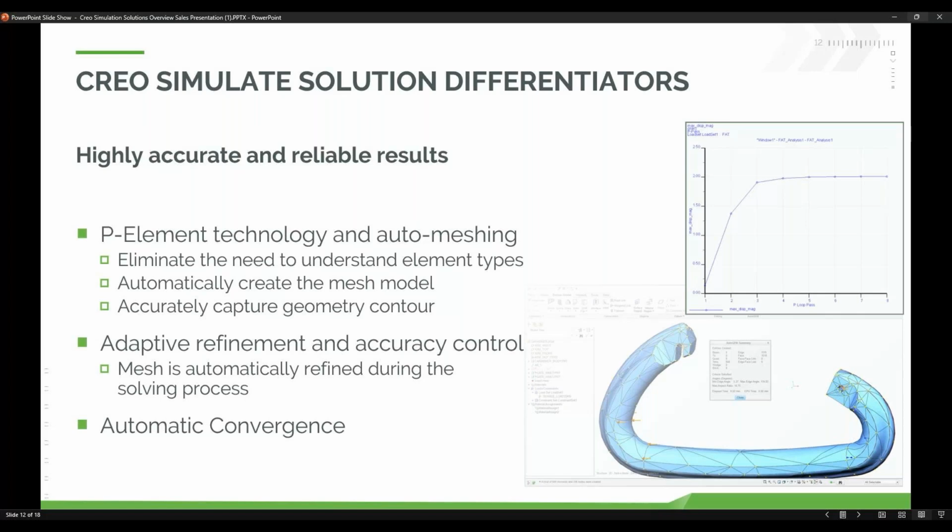Now, you can change the mesh by changing the parameters that are set up. What's a minimum edge, a maximum edge, a minimum angle, a maximum angle. Or you can do what's called seeding the mesh. If it finds a point or a line or an edge or a surface, it stops. So if I've got one big surface, this 2 by 2, it could be one element. I put some points on the edges. Each one of those points is going to be the end point of an element. So I can increase my element count by doing what's called seeding the mesh. That's all done automatically within the system.